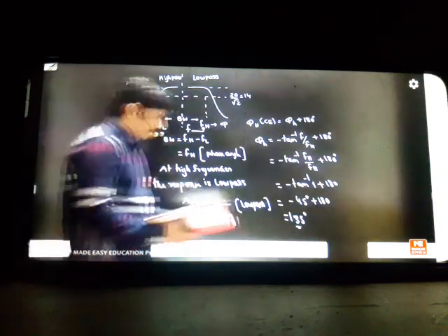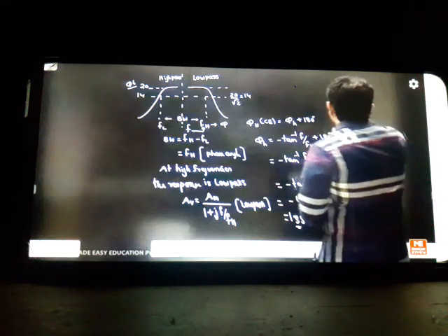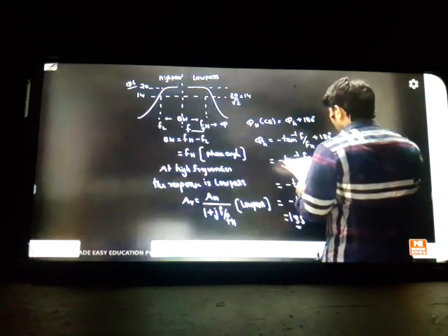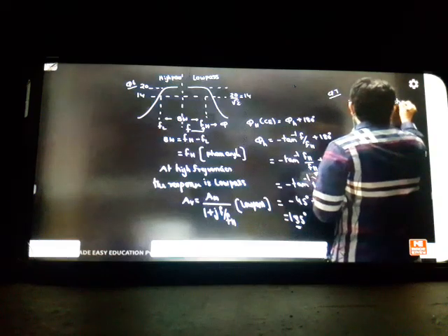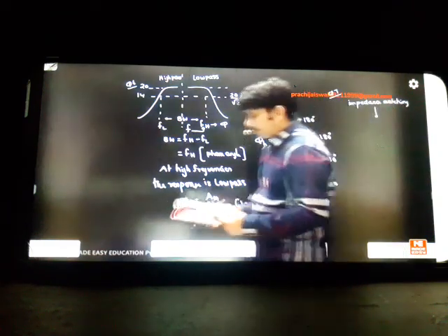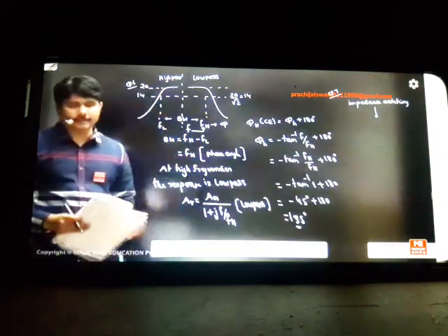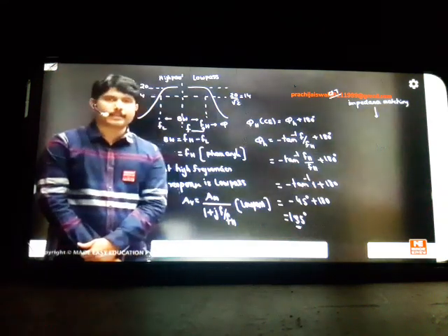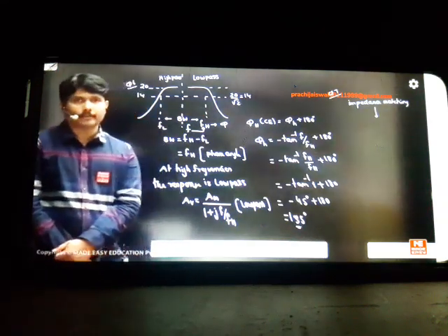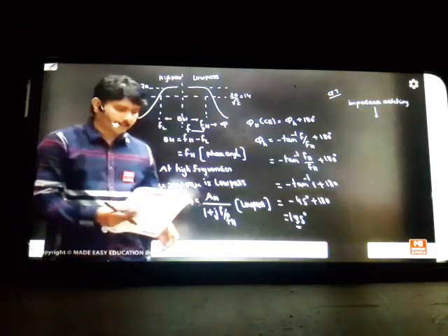Question 6 is completed. Question 7 is a theory question. Already in the previous class I explained this concept called impedance matching. So why do we use impedance matching? Yesterday, in the instrumentation amplifier topic, I explained the last concept: the amplifier should connect to a loudspeaker. Whenever you connect a loudspeaker, the loudspeaker impedance is very small, so my amplifier output impedance should be small. So a buffer is better there, I said common collector. So what is the purpose of impedance matching?